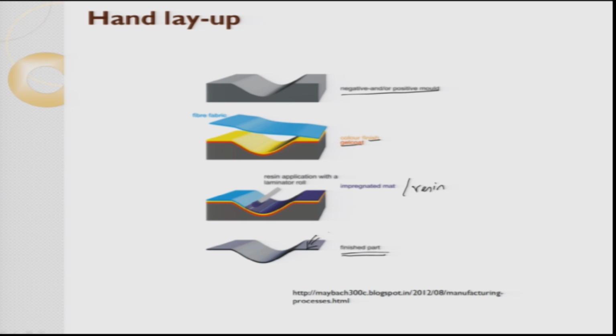So, this surface is non-functional and this surface is the functional surface. You always worry about a smooth finish. Of course, with composites you can't make micron accuracy; we always have a liberal tolerance, maybe plus or minus 1 millimeter, because the polymer shrinks and the fiber also sometimes gets slightly oriented here and there, so we make sure of that.